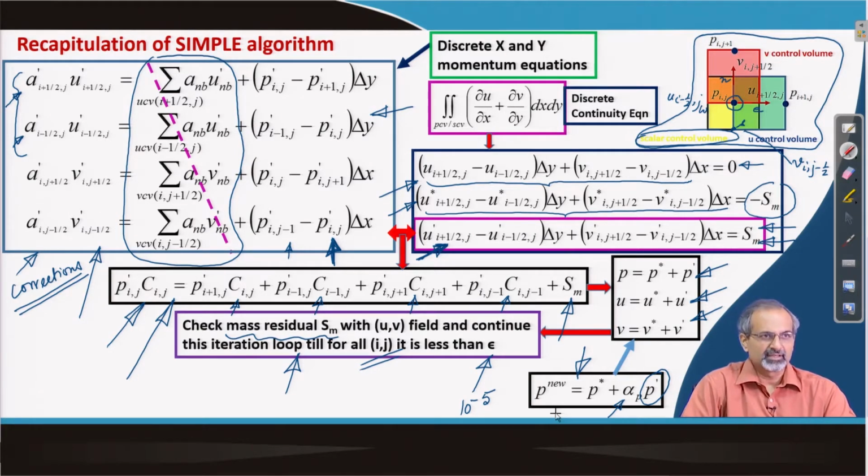behavior of the scheme. So, this is broadly what the SIMPLE algorithm is all about, and this process of pressure and velocity corrections will go on till you have essentially reached a near divergence free field, and you stop at a suitable point below which reducing the residuals becomes very costly.